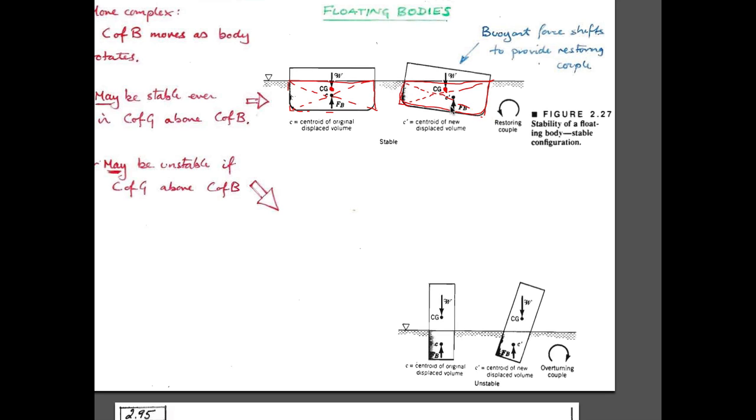Perhaps I should rescind that point. The center of buoyancy will be on the centroid of this submerged volume, where that is. And in this particular case, the center of buoyancy, with the force acting upwards, and the center of gravity with the force acting downwards, intrinsically tends to right this ship, which is what you'd like, right, if you're traveling on this.